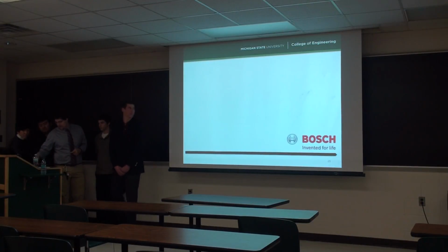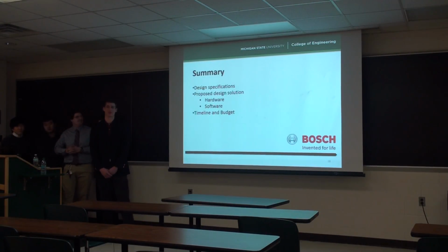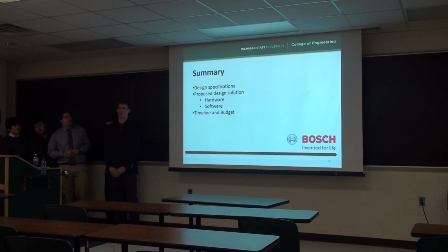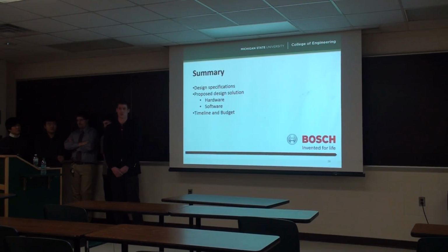Oh, we skipped over the summary, but there we go. Pretty much there are two components, the hardware and the software. The hardware is going to be the rectifier, which leads to the buck DC converter, which leads to the device under test. And that is going to simulate the waveform profiles entered into the PC application, sent over USB to the microcontroller, thus sending pulses to the MOSFET and simulating those profiles.